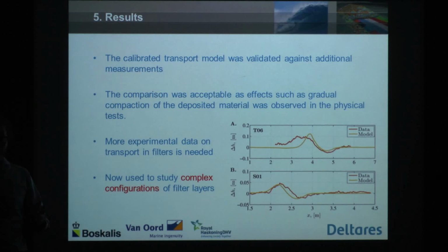Or do we need geotextile on part of the slope, and can we leave another part without geotextile, preferably the part that is always wetted because it's hard to install geotextile below water? So how can we optimize the installation process, design, and the lifetime of the structure?